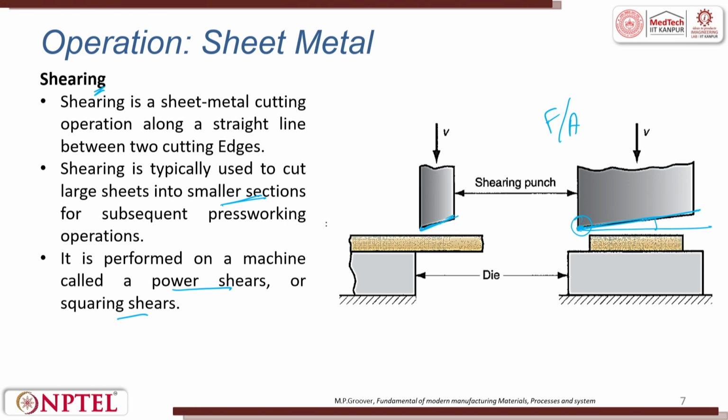Because of the stress, the initiation of the crack, or initiation of the shearing, can start, after which it goes all along the length before it finally shears. So, shearing will always have a taper. It is very important, and if you have a very thin punch, this will lead to bending. In order to avoid that, we have this taper edge and a thick plate.